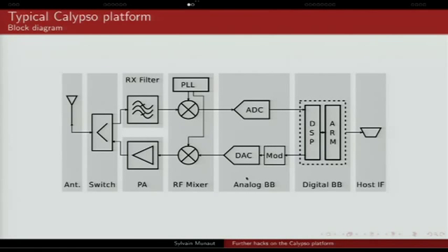One thing to note, though, is this block. That's a hardware modulation unit. So in the receive path, it pretty much acts like a software-defined radio. All the demodulation stuff is implemented entirely in software in the DSP. While for the transmit path, the modulation is actually done in hardware, which means the transmit path is slightly less flexible than the receive path. For our purposes, it doesn't really matter that much because, well, all the bursts use the same modulation, which means we can use that hardware modulator without too much issue.